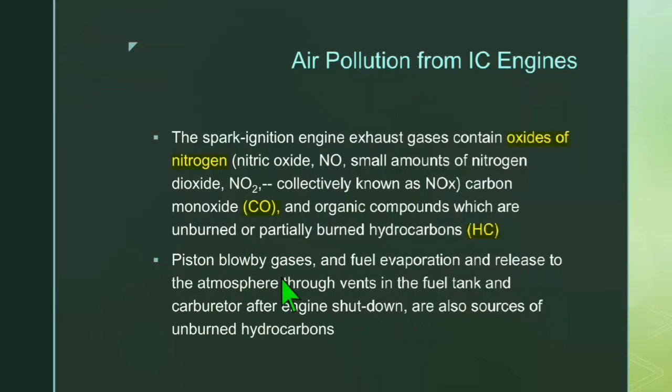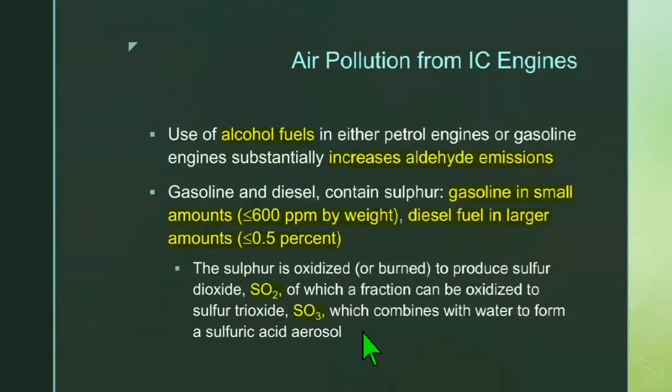Piston blow-by gases and fuel evaporation and release to the atmosphere through vents in the fuel tank and carburetor after engine shutdown are also sources of unburnt hydrocarbons. Use of alcohol fuels in either petrol engines or gasoline engines substantially increases aldehyde emission.